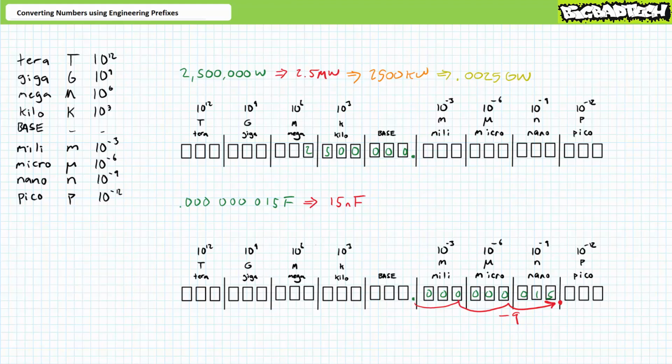We might run into some problems searching through the stockroom though, because no one makes a 15 nanofarad capacitor. For some unknown reason, the capacitor manufacturers of the world only very rarely specify capacitors in units of nanofarads, and customarily restrict themselves to using only microfarads or picofarads. Our task is to convert 15 nanofarads into an equivalent number of microfarads.